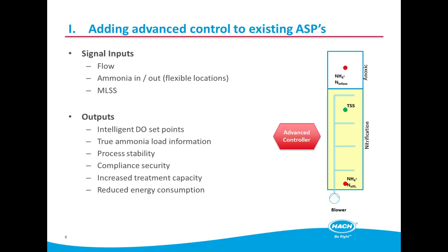So, commonly just say 3,000 milligrams per litre of mixed liquor. Now, the sludge age in winter at 3,000 is very different to the sludge age in summer. Even though it looks like the same conditions all year round, because you're hunting to a similar milligram per litre level in the aeration basin, you've got considerably different operating conditions throughout the year without even realizing it.